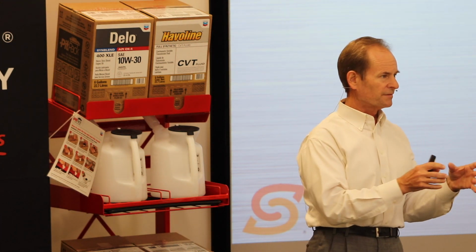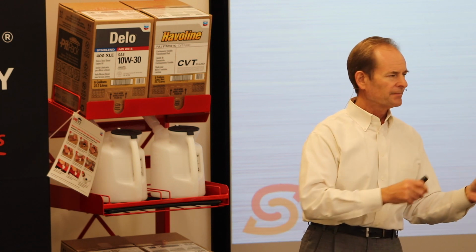Okay, we'll talk about a few other tests that are done on grease. The first I wanted to mention is base oil viscosity. Nobody takes a grease and, well, not nobody, it can be done, but it's a real pain, so it's seldom done. You take a grease and try to figure out what the base oil viscosity is, right? You can do that, but you have to break the thickener and clean it up.